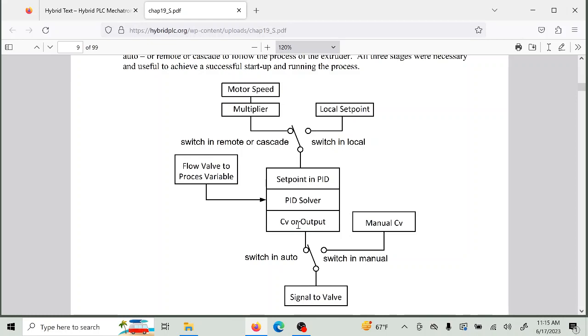He said maximum is 25. Well, I thought that would make it go faster. It made it go slower, and I didn't realize that. At this point in time, I never had done one of these before, and I basically phoned a friend, and I said, Alan, what do I do? He said, well, I think in that case that the TN term, it's the reciprocal, and bigger is slower, and small is faster. So I looked, and the minimum value is 0.2, put in 0.2, and the thing came right up to speed and was very responsive from that point on.